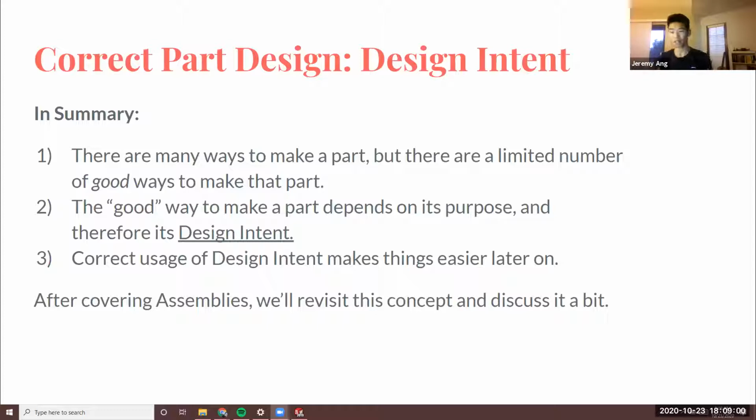that's an example of very, very poor design intent, because going back to the good way to make a part, the purpose of those holes is to be a certain distance from that giant cutout in the middle of the box, so you can mount the circuit board stack onto. Now, the good design intent would have the holes next to the cutout dimensioned a certain distance from the cutout. That way, wherever the cutout moves to, depending on what we need, the holes will always be right there, because the holes aren't going to need to be anywhere besides a certain X distance from the cutouts.